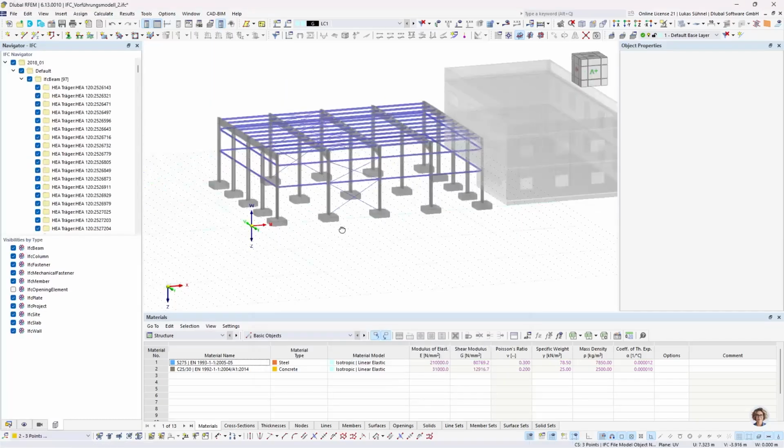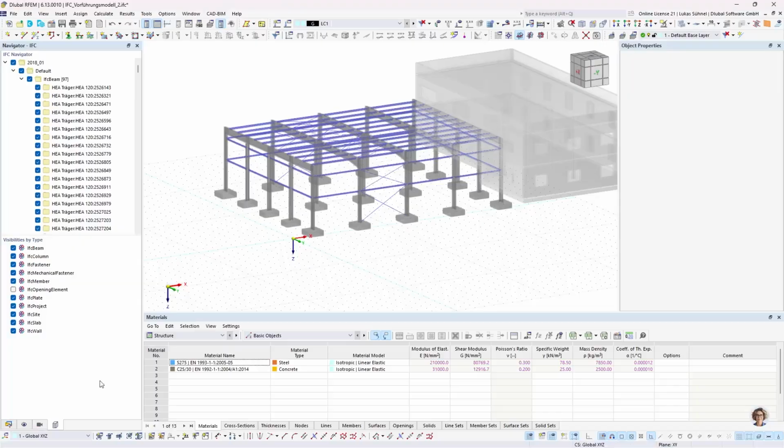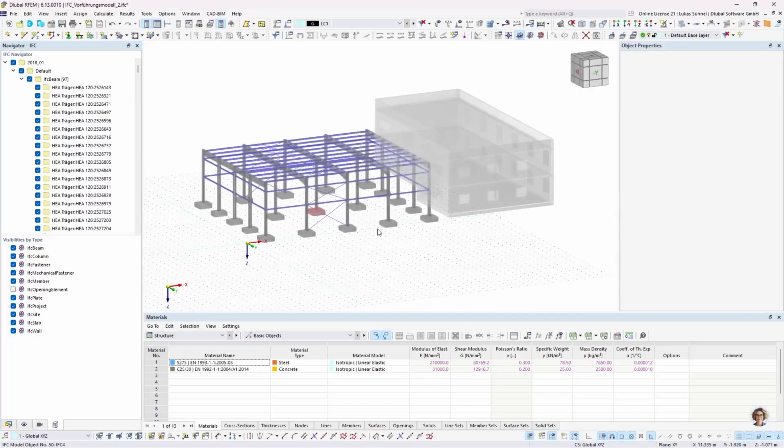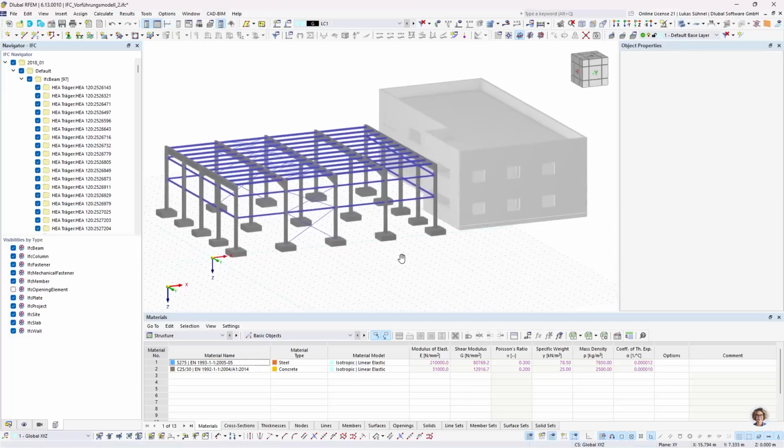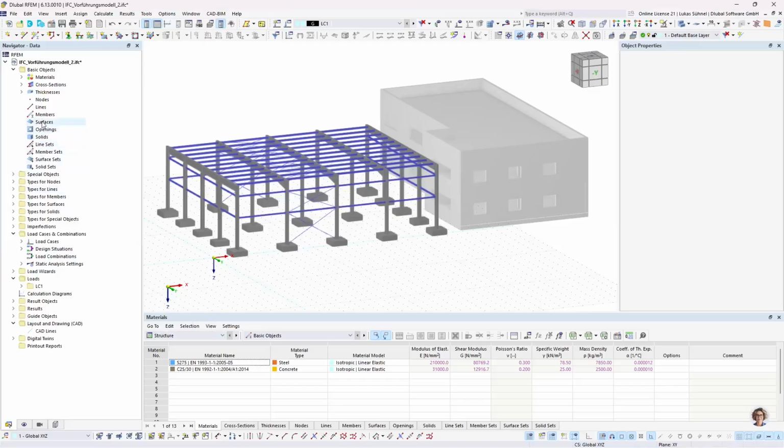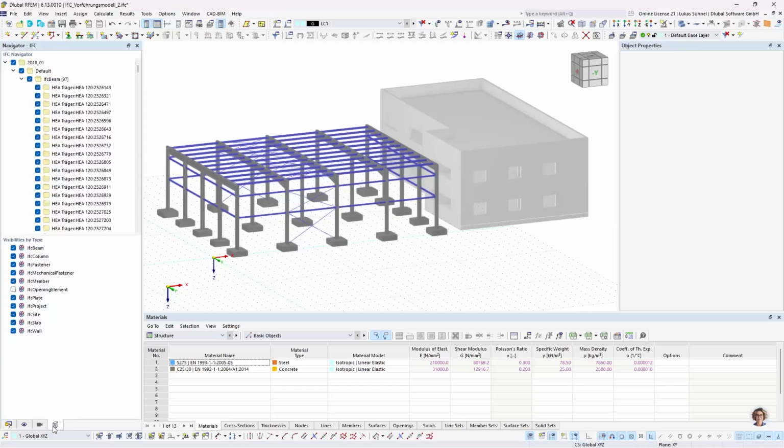All right. So that is the IFC file that we just imported, that we also saw in the BIM Vision viewer. And we can also show it inside Rfem 6. So what we currently see, this is no native data. We do not have any members. We don't have any surfaces. The objects that we see here, these are IFC objects, graphical objects. And we can display them because we have an IFC viewer integrated, as we can see here.